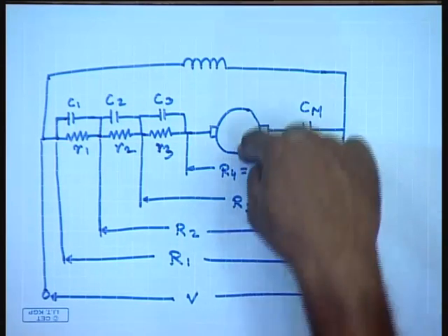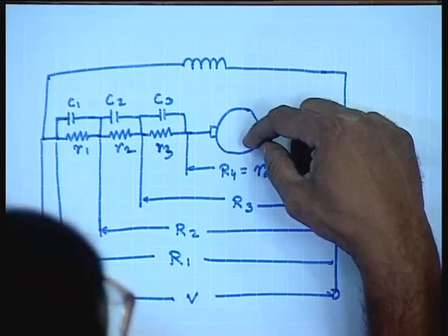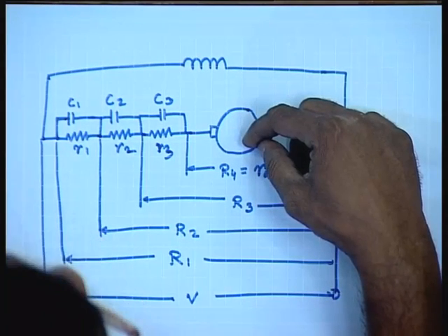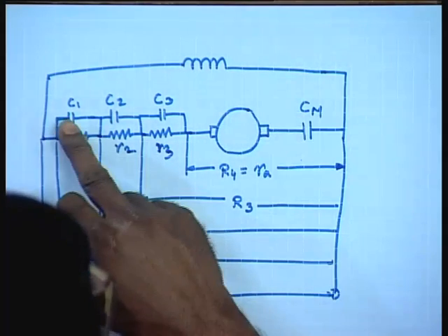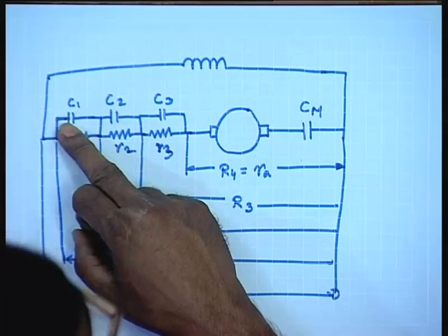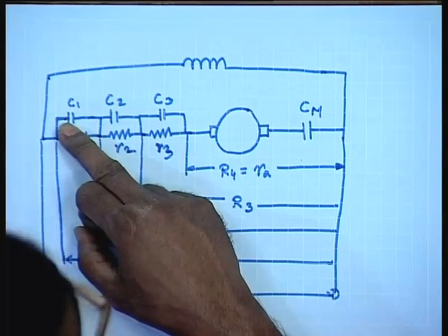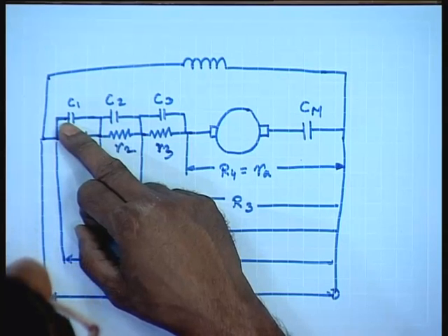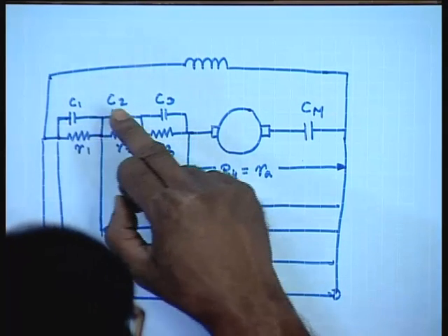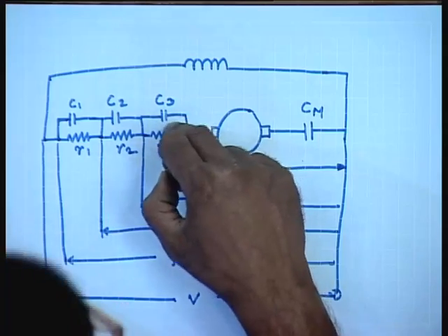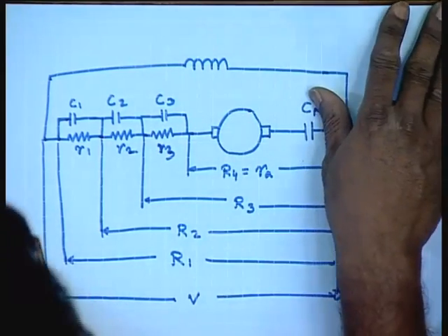After a certain time, when the machine current falls below a certain limit, the first contactor closes, the current immediately jumps and torque increases again. After some time C2 closes, after some time C3 closes, so that the machine comes to full speed.